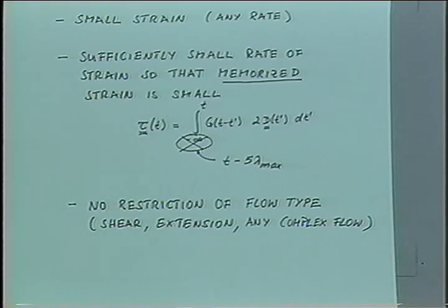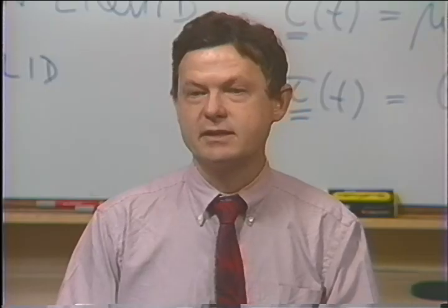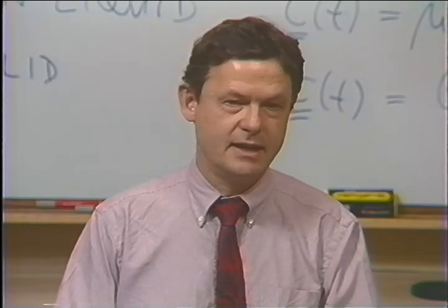When you talk about linear viscoelasticity, there's only one equation which describes everything. The limiting case of that for the pure liquid, the liquid which has zero memory, would be the Newtonian liquid. And the limiting case of the perfect memory where no relaxation occurs at all, where G is a constant, that's the Hookean solid. So those cases are included.